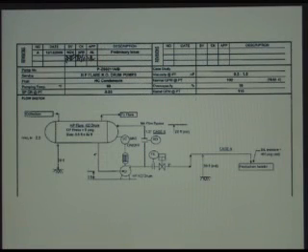So for this, it identifies the pump tag number and the service and what the fluid is going to be, the pumpage temperature, and specific gravities, viscosity, and then the normal pump flow rate plus a percentage of overcapacity. We always buy them a little bit big, and so the final flow rate is 110 GPM. The suction to the pump comes from a tank, which is 10 feet above grade. The pump center line is 2 foot above grade. This obviously changes from pump to pump. 2 foot's a really good starting assumption, though.